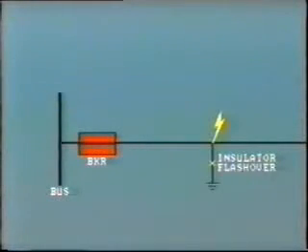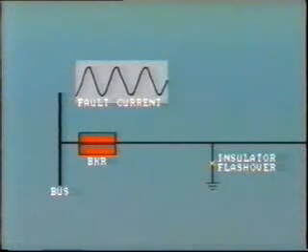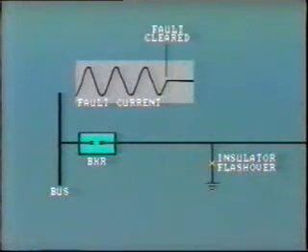Well, here's one way. A lightning strike to a phase conductor flashes over an insulator, causing a single line-to-ground fault. The breaker at the substation successfully clears the fault, but a very short time later, perhaps a few cycles, there is a second strike to the line. The resulting surge in voltage causes the open breaker contacts to restrike.